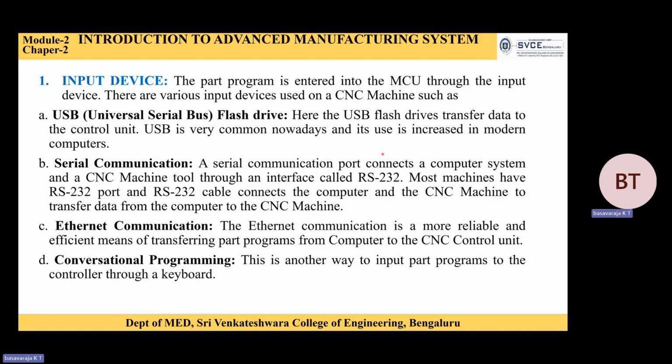Another input device is serial communication. A serial communication port connects the computer system and the CNC machine tool through an interface called RS232. Both the cable and the port should be RS232 interface only, then only it will be possible.